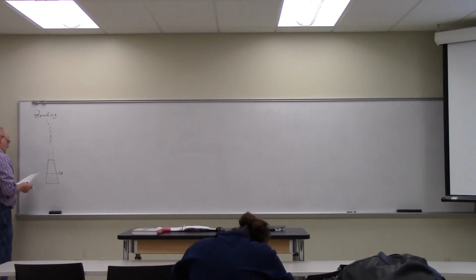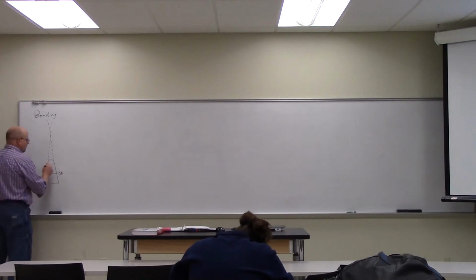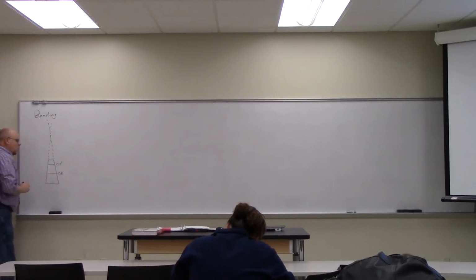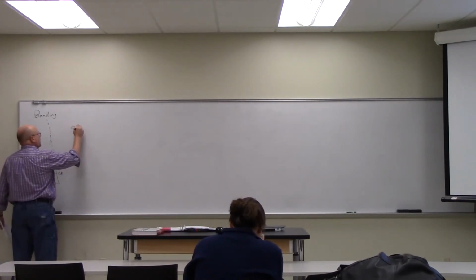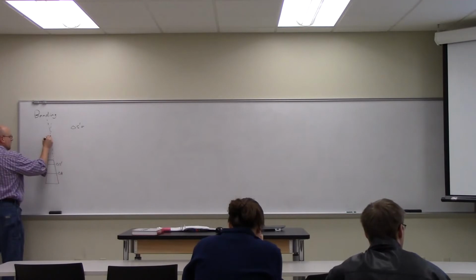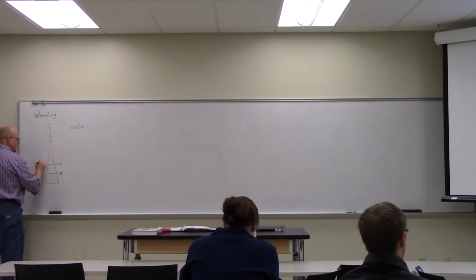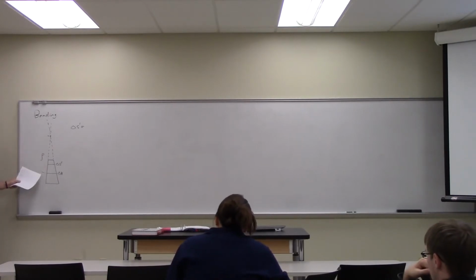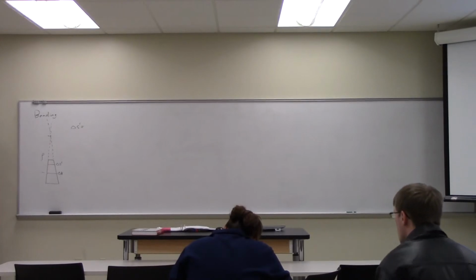And so that's the neutral axis, the plane that does not experience any tension or compression. But there's some dimension down here, labeled in the picture as delta S prime, I think, which is smaller than delta x. So we want to figure out the dimensions of delta S prime. We have this distance here, the radius of curvature, if you will, from the neutral axis back to the center of the curvature.